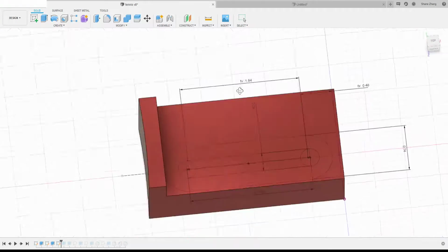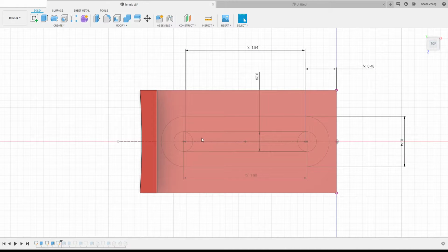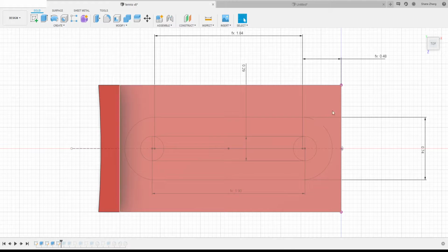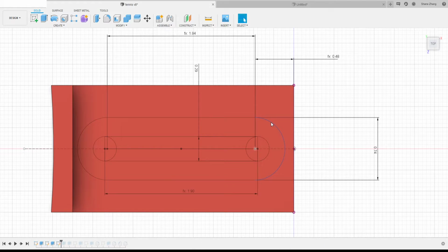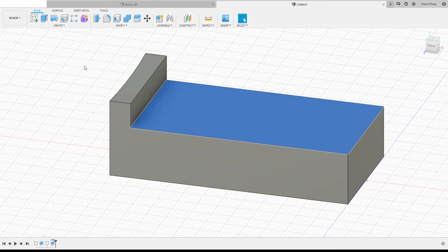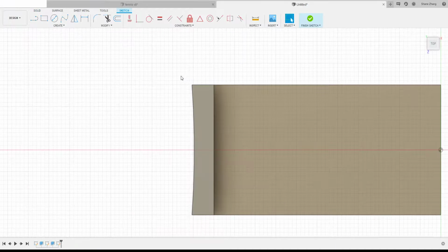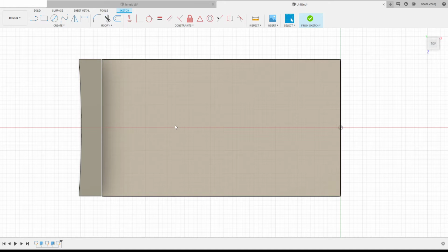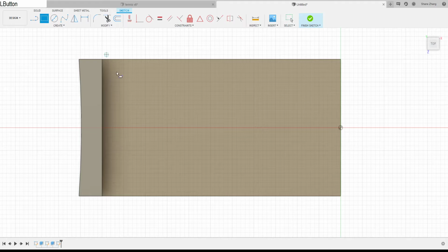So here's what I'm gonna do. And also I will separate those two sketches. So trying to figure out. We got this. Okay, so I would start a sketch on the top plane for the bigger profile. So pick the plane and start the sketch. And we have a mill slot. So let's see, we have a rectangle, 2 circles. And also this whole thing should be centered to the origin.